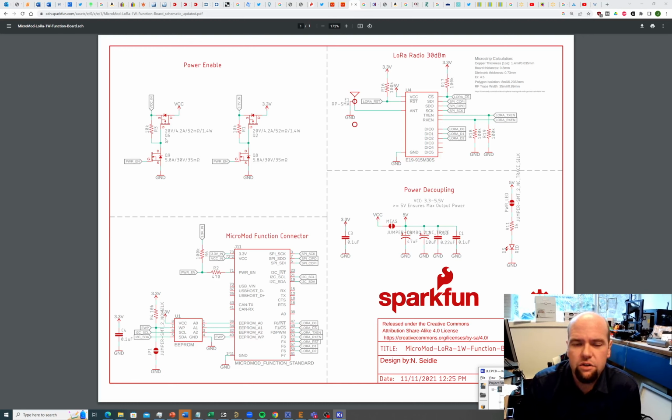This radio consumes about an amp at maximum current. Consuming that much current, it's nice to be able to fully cut power to it. It's nice sometimes to be able to control it by fully cutting the power to do resets when resets might not work, or just for saving power. So some of you might have peripheral boards that have a bunch of different stuff on them. A good way to make sure they're going into real low power mode is to just totally cut power. So we're going to copy this, looking at this.